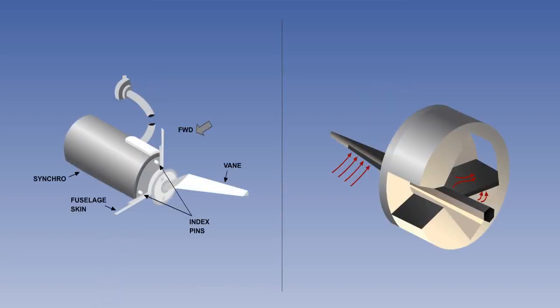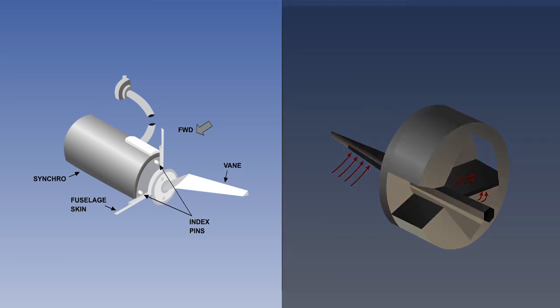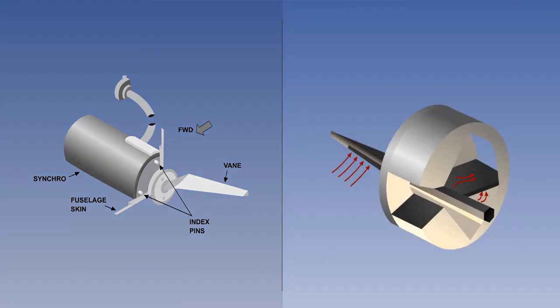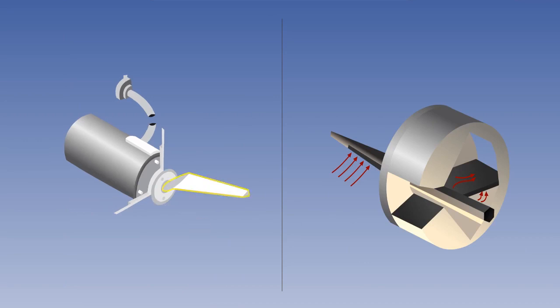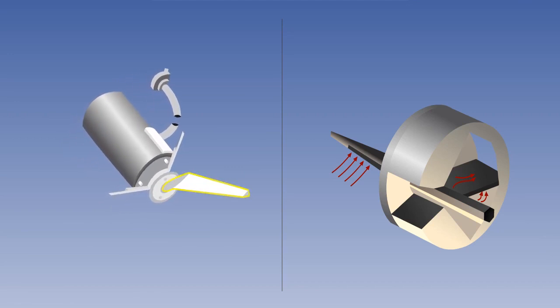As previously mentioned during the components phase, we are now going to learn about the angle of attack sensing probes. They are positioned on each side of the forward fuselage with two basic types in use: a vane type or a conical slotted probe. Both are protected against ice formation by a heater. The vane detector is a counterbalanced aerodynamic vane, which positions the rotor of a synchro, which is used to measure the subsequent angle.